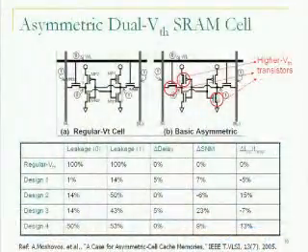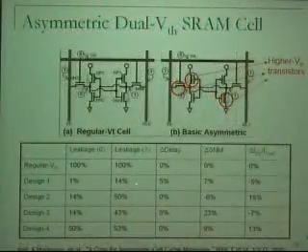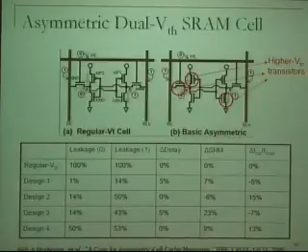So presumably there would be some kind of trade-off in that regime. Yeah, maybe it helps here. You have some trade-off. Yes, you reduce leakage 0 and leakage 1 here, but you also have delta delay. So the speed of the SRAM cell is also getting impacted or changed, at least here.